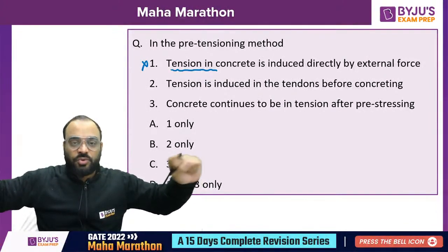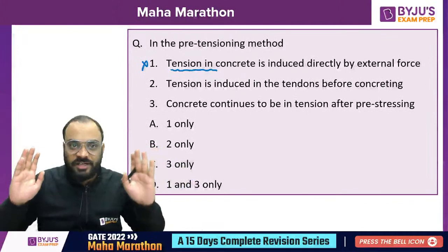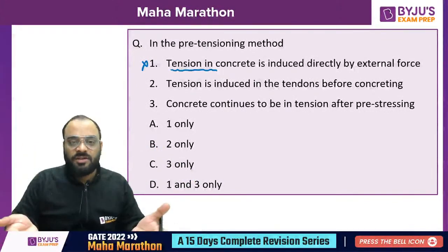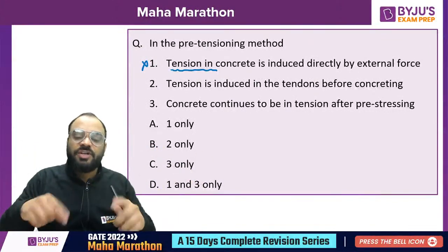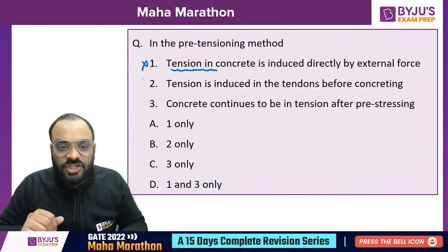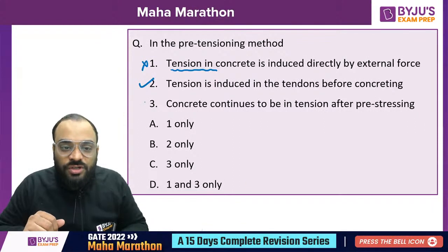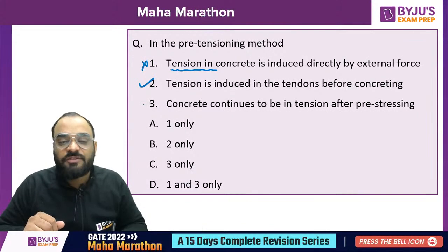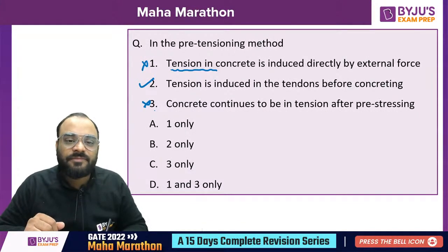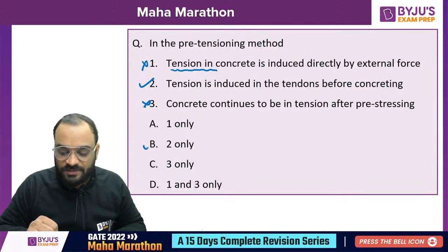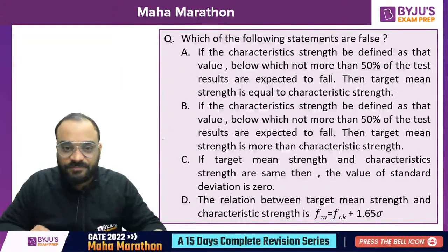Then, as per Newton's third law, equal and opposite reaction will develop. That means the compression force will develop, which is transferred to the concrete. So tension is induced in the tendon before concreting. Yes, it is correct. Concrete continues to be in tension after pre-stressing? No, guys. That's why B is the correct answer.